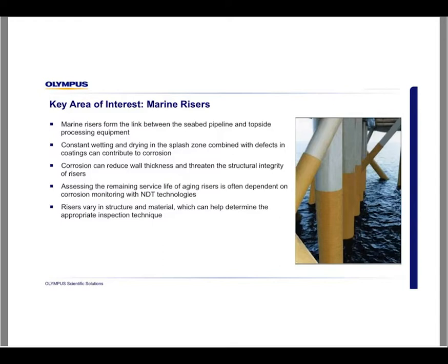Corrosion is of concern to platform managers and inspectors because it can reduce the wall thickness and threaten the structural integrity of risers. And it's important to assess the remaining service life of aging risers, and this assessment or determination of the structural integrity of a riser is often dependent on corrosion monitoring with NDT technologies. Now, riser structures can vary in structure and material, and the makeup of the riser can help determine which ultrasonic or non-destructive testing method is appropriate.